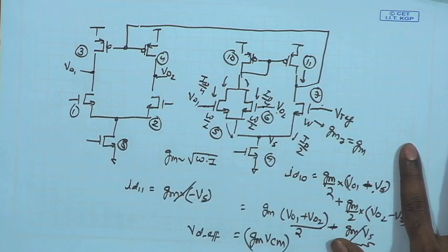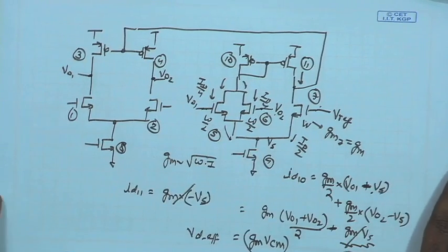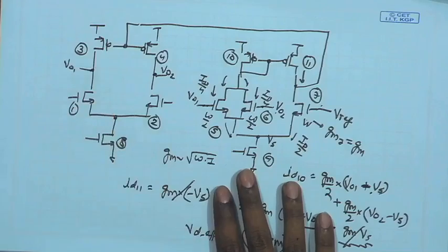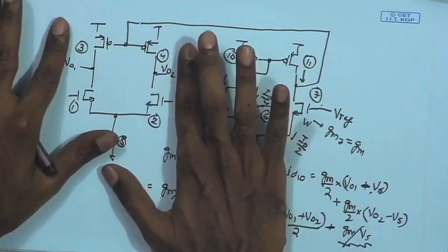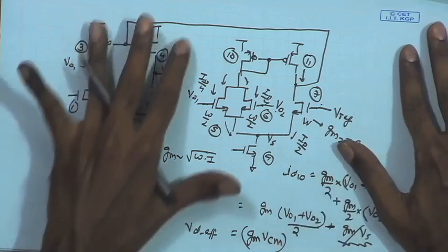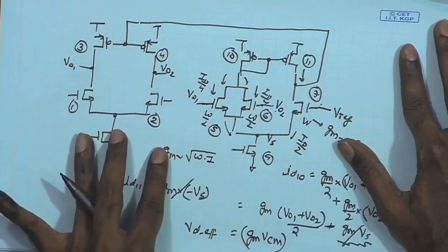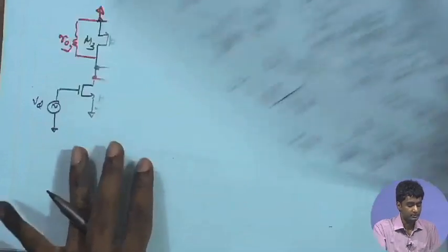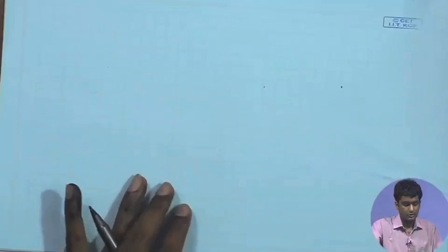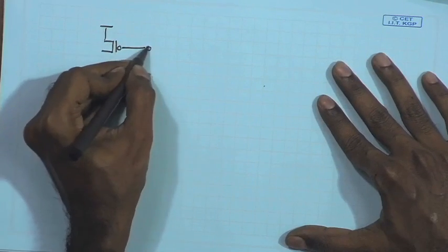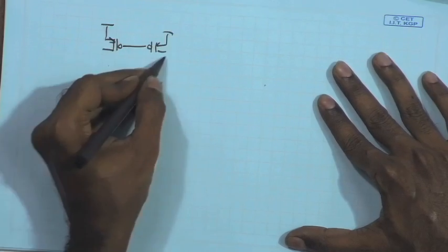Now, in general, when we go for operational amplifier design, we know that we will be needing multiple stages. We will need at least 2 stages in a given operational amplifier to get a larger gain, and the second stage is also active load and fully differential. So, how do we incorporate common mode feedback in such a case? We can look at that scenario where we have a fully differential op amp with 2 stage amplification.